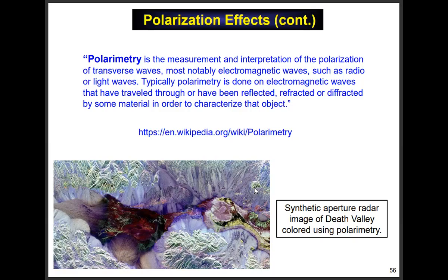And I think I mentioned this one day, but another example is like the base station antennas for your cell phones. So the base station antennas most typically transmit and receive in what's called dual slant 45 polarization. If you open up a housing and you look at the antennas on a base station tower, you'll see a typical array of dipole antennas, and there'll be one like this. Say it's 45 degrees from vertical, right? It's called slant 45. Not horizontal, not vertical, 45. And then, one antenna that looks like this, and the other antenna that looks like this, and an array of these, right? So slant 45 polarization.